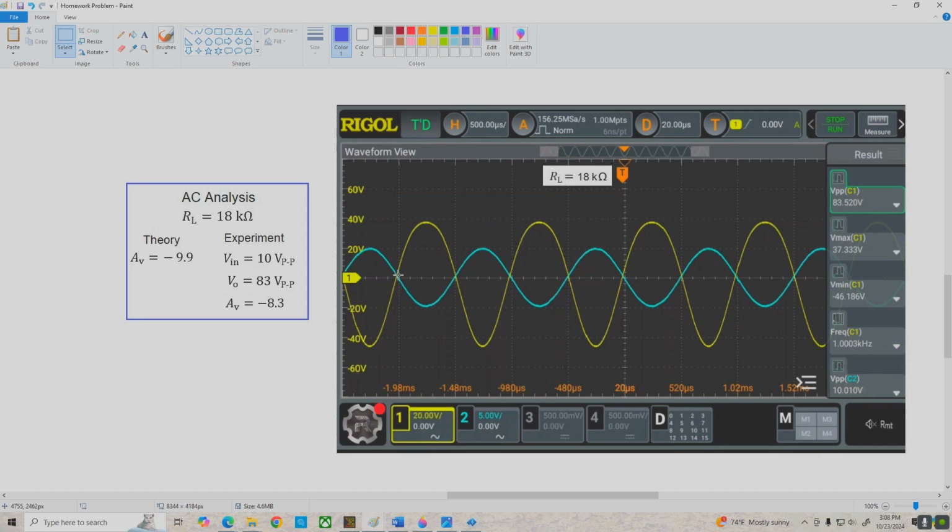You can see the gain to negative going inputs is less than the gain to positive going inputs, resulting in the squashing and stretching effect that we also saw with bipolar transistors and field effect transistors in this Class A amplifier configuration.